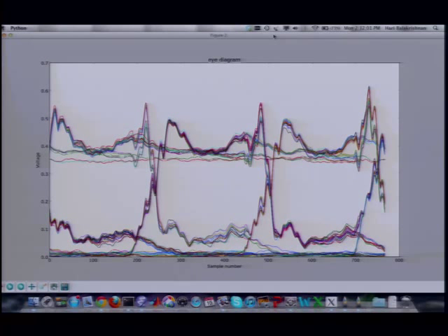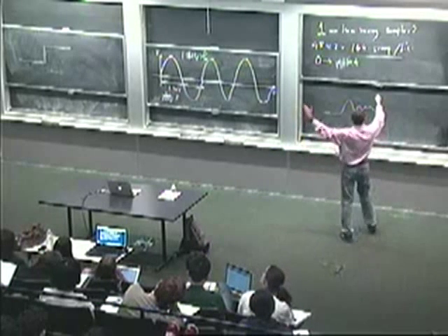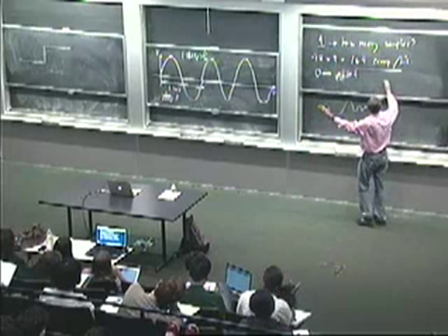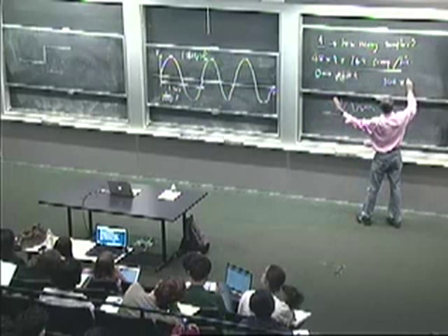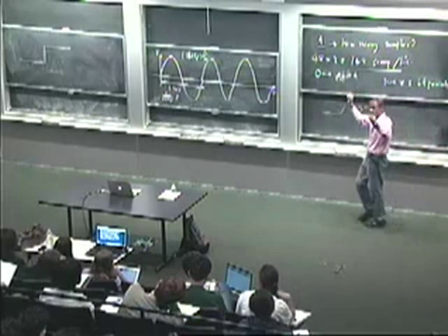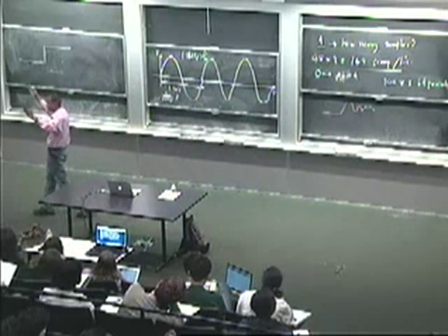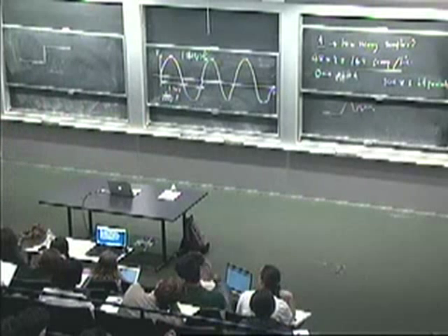The output of the demodulation is a set of voltage values. What you do is you look at 3-bit periods. In other words, you look at a sequence of time, a number of samples that corresponds to 3-bit periods. So for example, if I pick 144 samples per bit, I take 144 and multiply that by 3-bit periods, and I look at that many samples. So for every 3-bit periods, I take all the samples and I plot them.